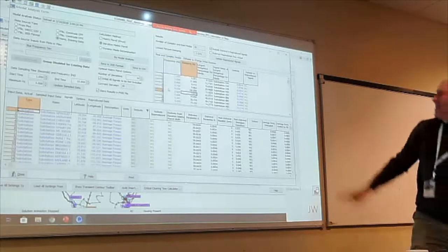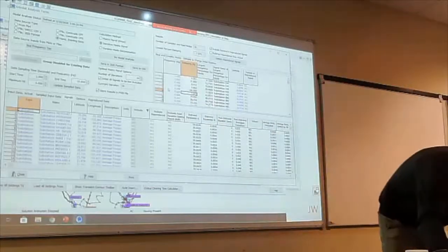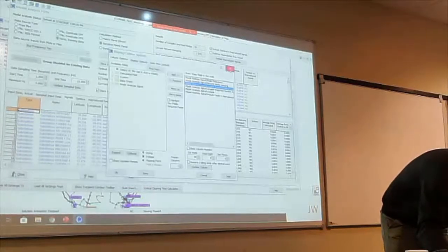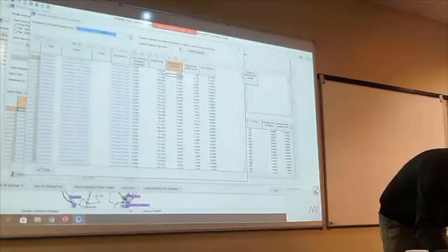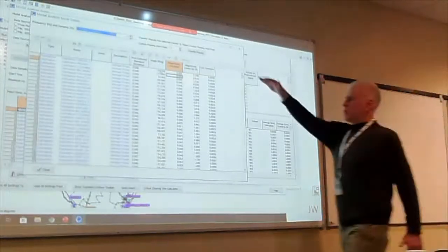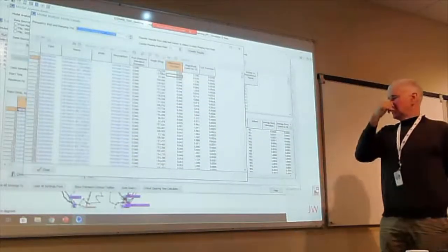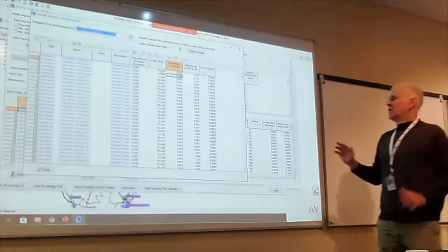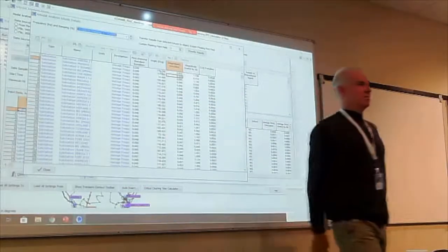Then here, you can sort by damping. We're looking at the one that's got the 628. Yeah, 628. If you right click on that, oops, I clicked on the wrong one. Right click on that, show dialog, then it has this data here, which is showing for each substation how that substation's frequency participated in that mode. And it's a complex number. It's a magnitude and an angle, so it's a vector.